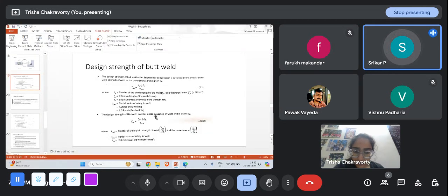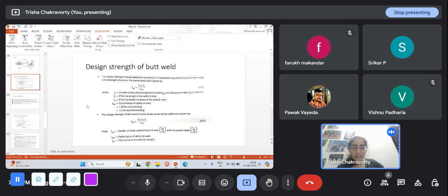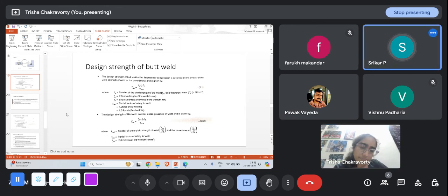See, the word yield, it doesn't matter. Yield does not depend on whether it's tension or shear. Yielding is when the yield stress Fy is exceeded. Every steel material has a yield stress Fy. When that is exceeded, it doesn't matter whether the stress is generated by tension or shear or bearing or anything.